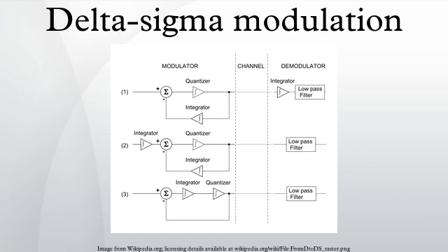In this case, a multi-bit digital number is input to the delta-sigma modulator, which converts it into a faster sequence of zeros and ones. These zeros and ones are then converted into analog voltages. The conversion, usually with MOSFET drivers, is very efficient in terms of power because the drivers are usually either fully on or fully off, and in these states have low power loss.